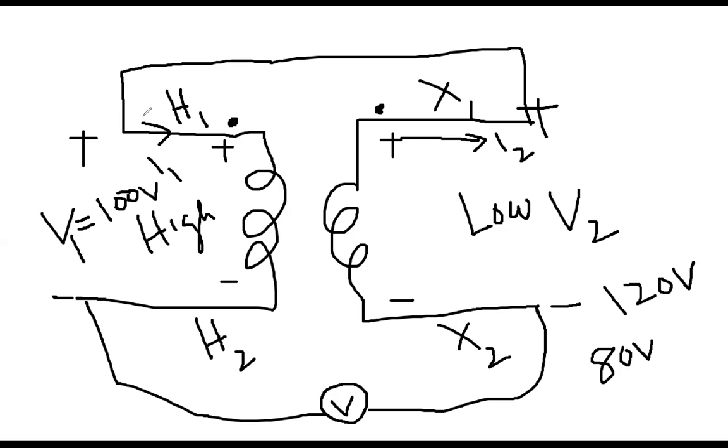And you remember, this I just made shorted. This means I threw a wire and connected these two terminals, and I have added a voltmeter between this point and this point. Now these two coils are fully in series, and then I got the higher rating. So what does that mean?